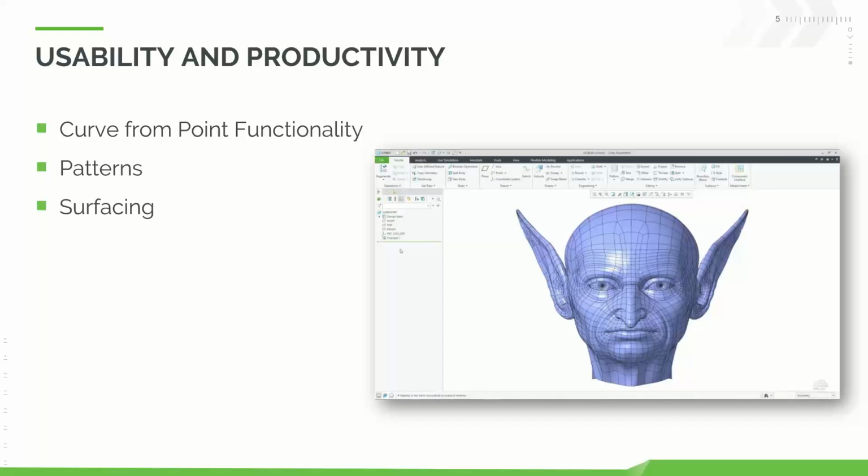Some improvements in surfacing as well. This means better control over the curve definition, specifically around curvature and acceleration control points. You can now grab those, see them, make it easier to get those curves exactly the way that you want. And also now into working with the freestyle tool, you can now smooth and simplify curves. We have a new brush capability for working with that, for really sculpting that organic shape. I'll go through and show a demonstration of this, but it's a very, very useful tool. Also the ability to mirror shapes inside of freestyle, that got an update, so definitely a lot of additions there.